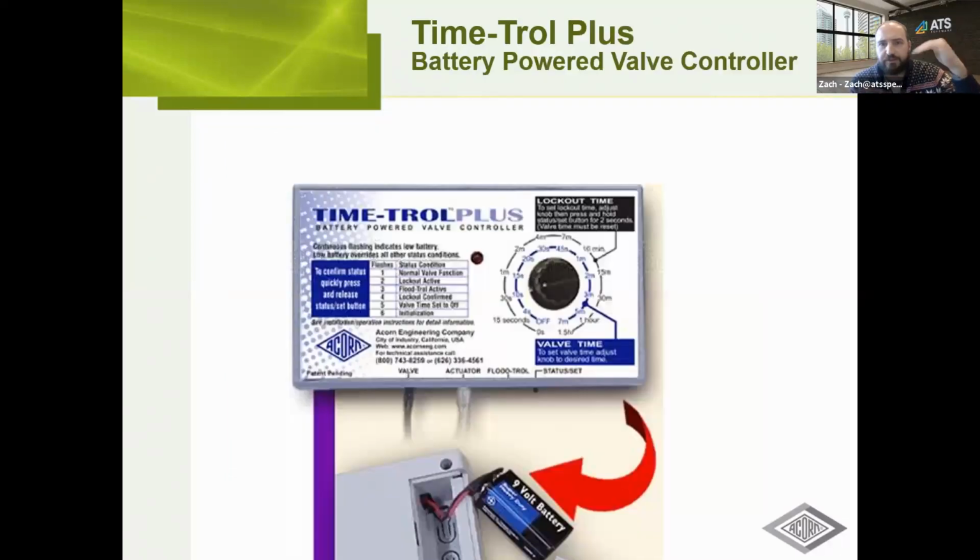So to break that down a little, say you have a combination unit, you would never have a situation where, say, the hot and cold on the lav is used with Time-Trol, but the flush valve is controlled by Master-Trol. They're all going to be one or the other, right? Correct. Because if you had the Master-Trol controller, and just for the sake of argument, you had a computer, there's no way to hook up the Time-Trol to the computer.